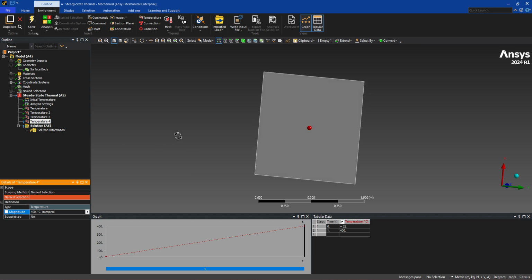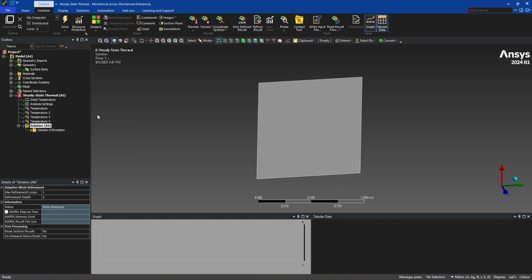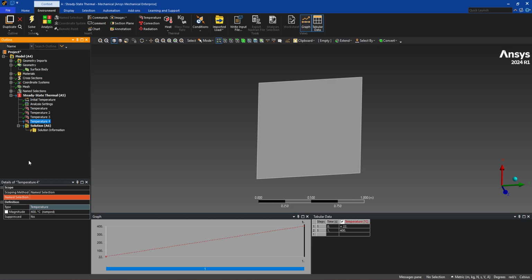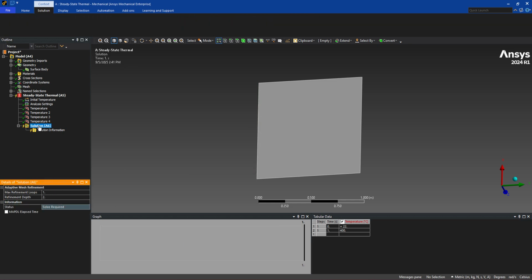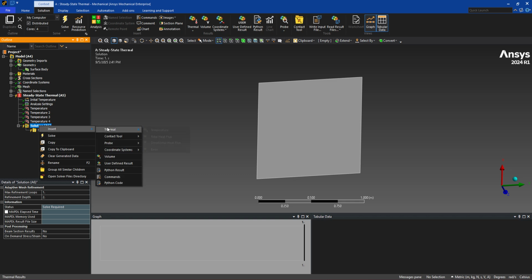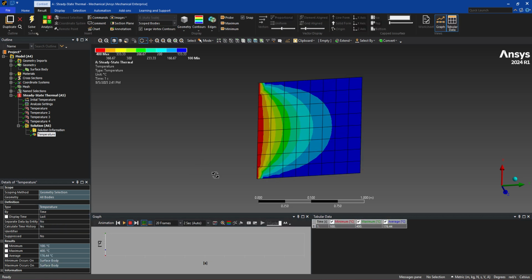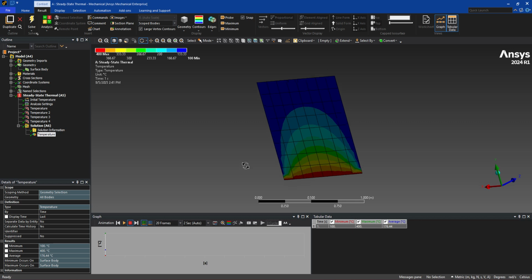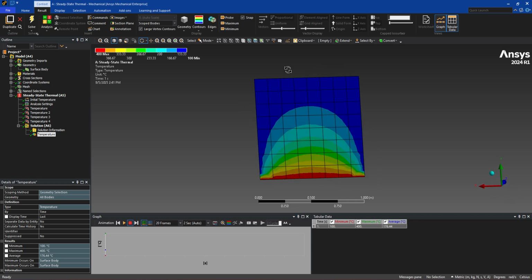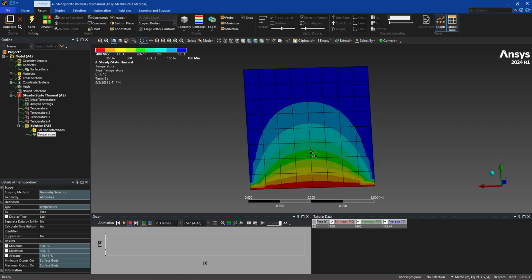And as we will be seeing the temperature distribution, go for solution. Wait a minute, it shows a problem mark, lower. Okay, right click in solution, go for thermal and temperature, and now solve it. And you should see a similar type of temperature distribution in this plate.